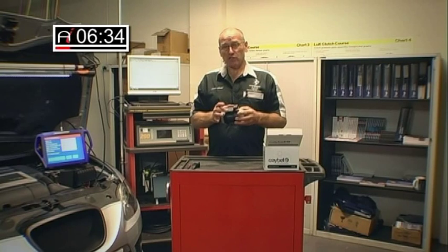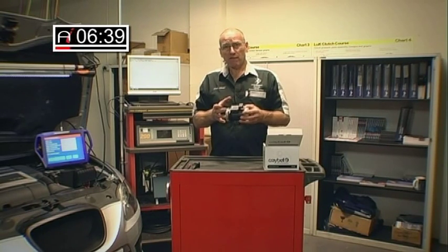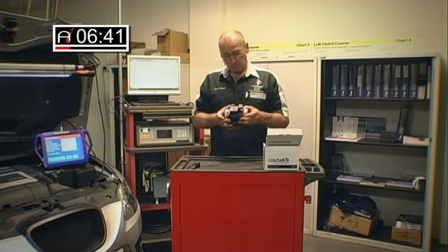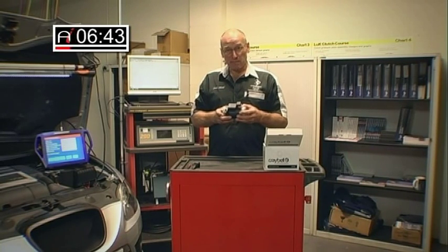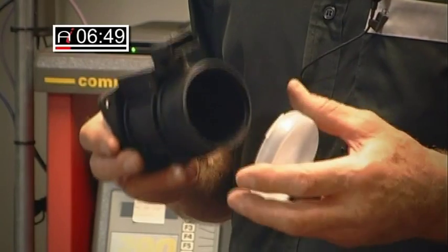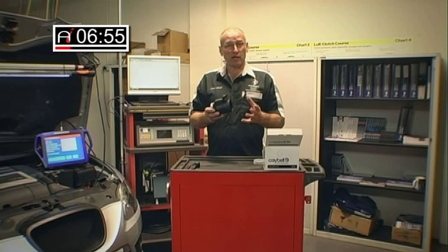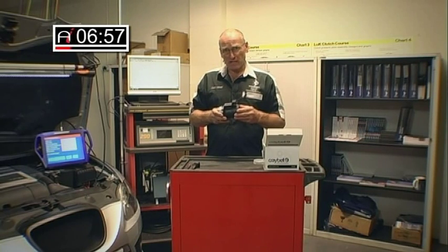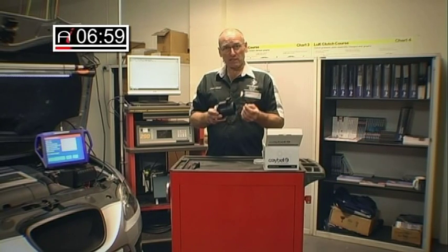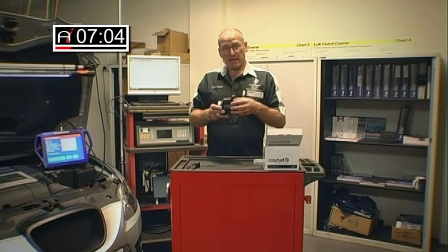And the biggest single cause is emissions, breathing, fumes, deposits of oil, which are often recirculated as part of the breathing system of the engine, often become contaminated on the air mass meter. And this can happen when you actually turn the key off. Once you've turned the key off, the oil in the sump's quite hot. It causes vapour to rise. Within that vapour are particles of oil, and that can find its way back into the induction system.